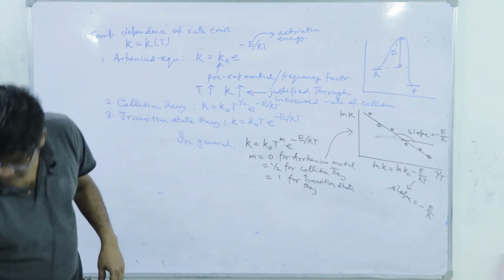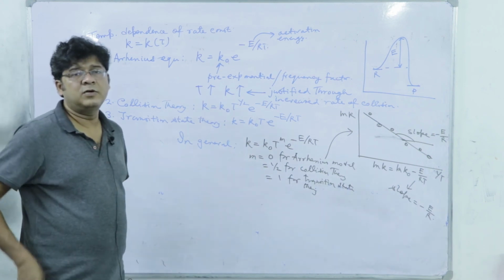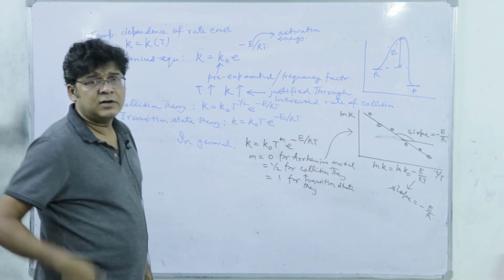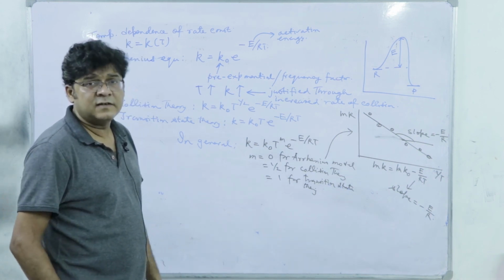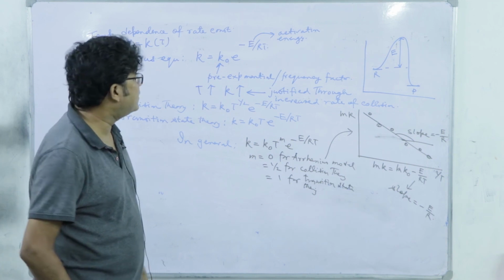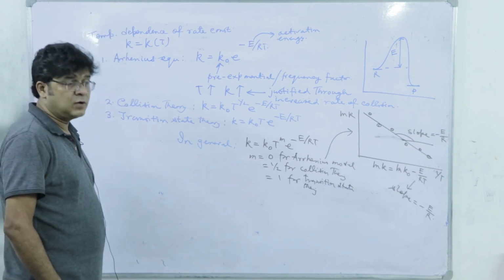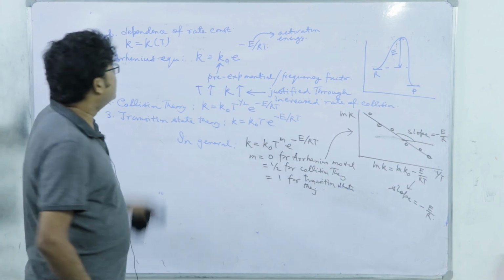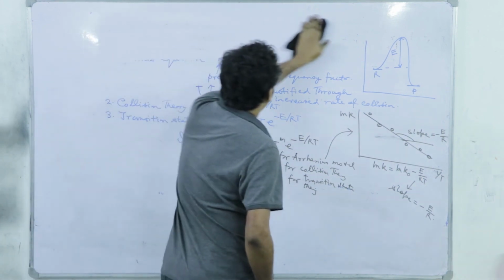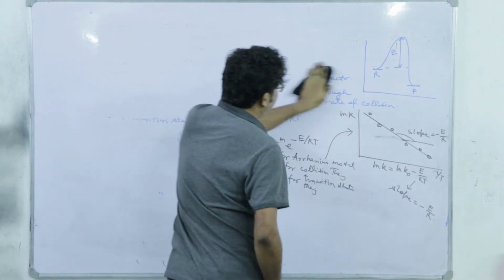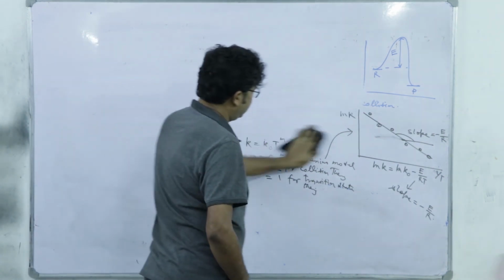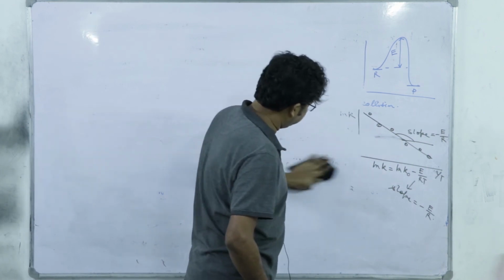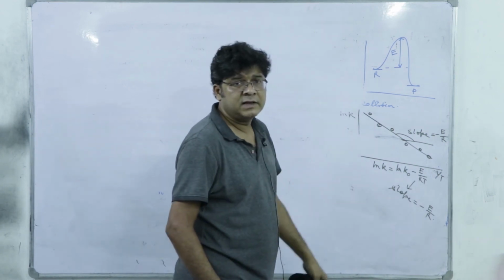In the second session, we are going to discuss the interpretation of batch reactor data, because to model or to design any reactor, it is necessary to understand the rate equation. So, the question is how to derive a rate equation when we do not know whether it is first order, second order, elementary or non-elementary. Under this condition, we have to employ a batch reactor, analyze the kinetics by generating data, and then develop a kinetic model which can universally represent the rate of the reaction.